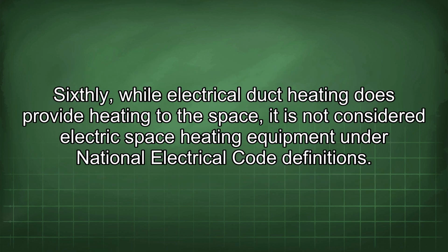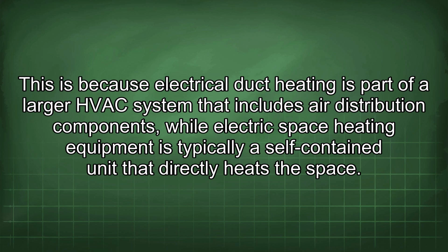Sixthly, while electrical duct heating does provide heating to the space, it is not considered electric space heating equipment under National Electrical Code definitions. This is because electrical duct heating is part of a larger HVAC system that includes air distribution components, while electric space heating equipment is typically a self-contained unit that directly heats the space.